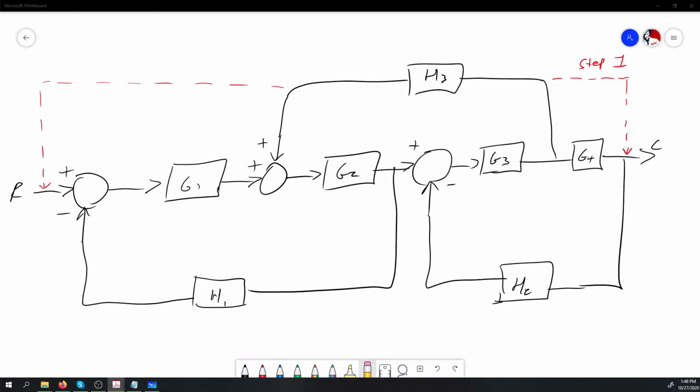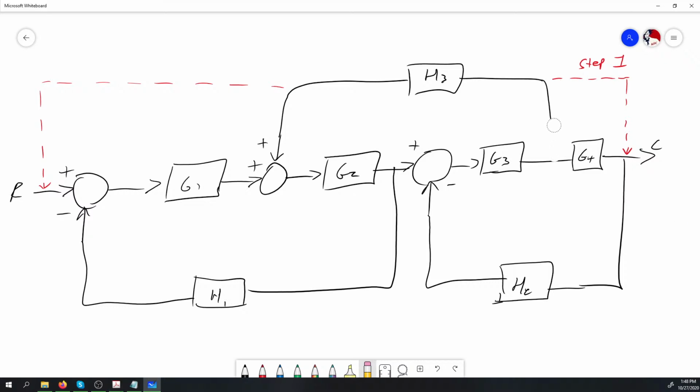Right. So in moving our first takeoff point here from the left of G4 to the right of G4, that means that for this affected block here, we're going to have a 1 on G4 component occur. So if we erase this and then put that takeoff point where it's required, that means we're going to have 1 on G4 here.